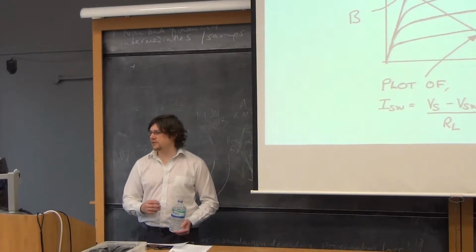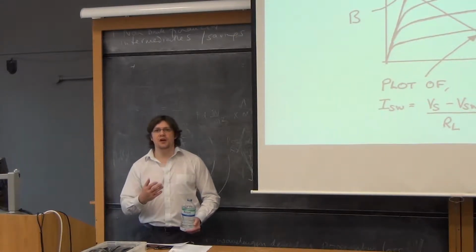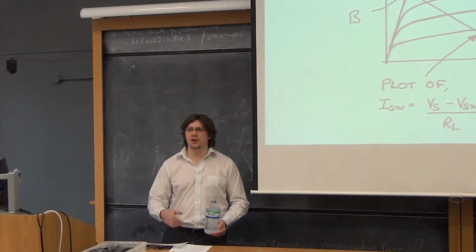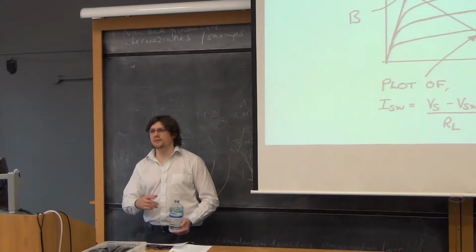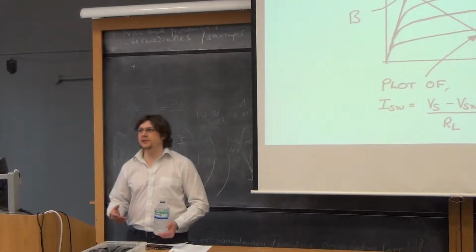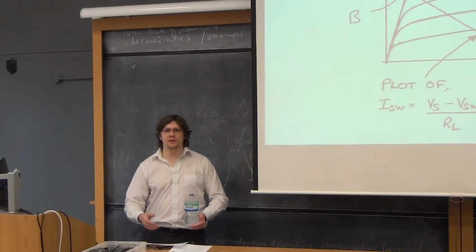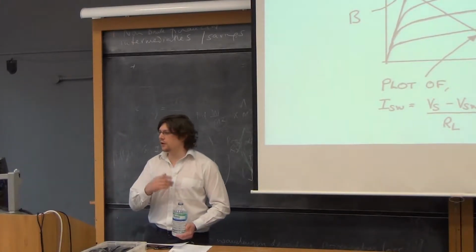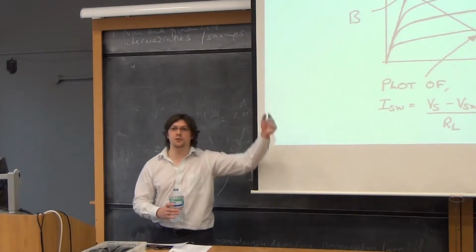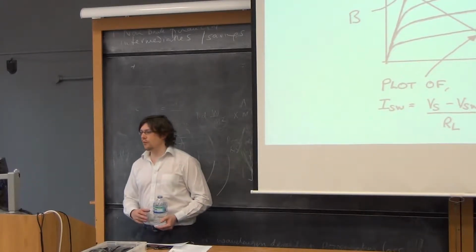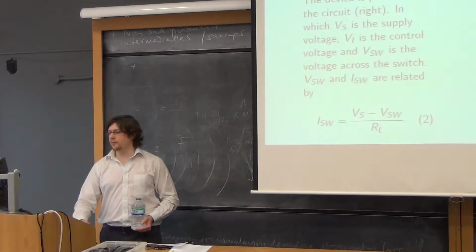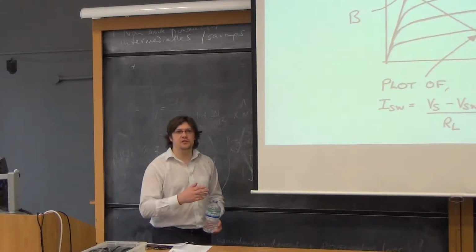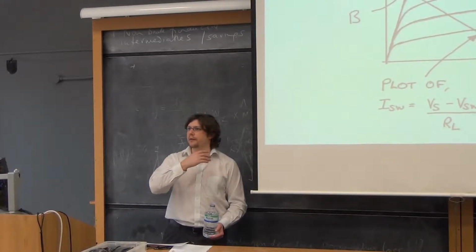Now, if I had a graph of volts and amps, and I had a resistor, I could plot on that graph a line which would represent that resistor, because Ohm's law says that the line will be straight, and R is related to V and I by a factor R. So the slope of the line, in fact it's 1 over the slope of the line, gives us what R is, and this is the R that we already know about because it's RL. So we can only go where the characteristics will let us. We can't just pick a point.